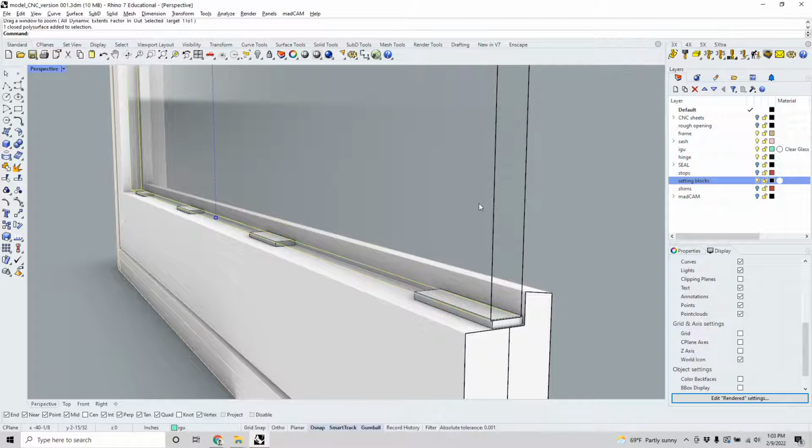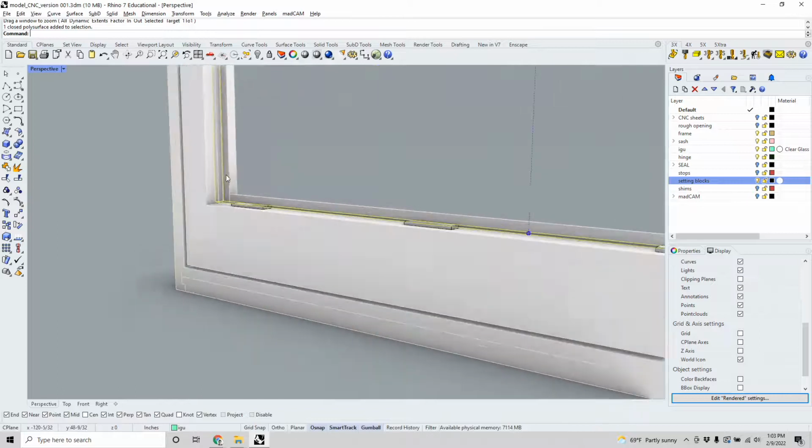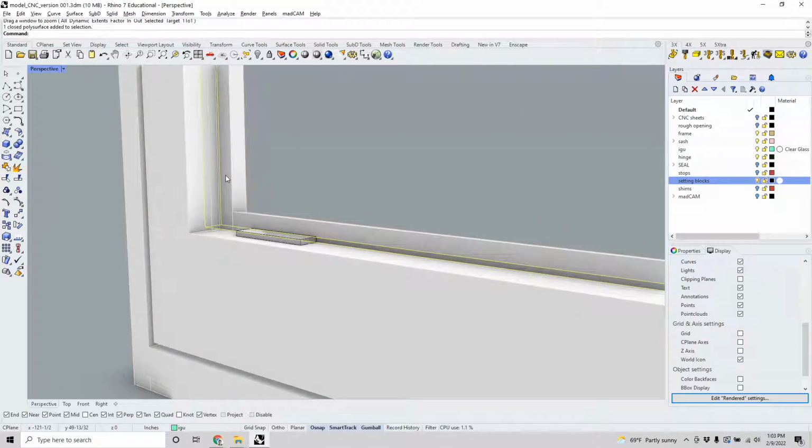So in terms of the glass, mine is a half-inch thick, double-sided insulated glazing unit with a low E coating. The low E coating I use is Solar Band 60. So around here, you can get Solar Band 60, Solar Band 70, and so on. And in other places, you might want to even go with triple pane glass, but that's a much heavier sash. I'm going with this double pane glass. You can't order it from the IGU fabricator directly. You need some kind of special glazing license, which I don't have. So I order it from local shops like Ace Glass around here in the San Francisco area.